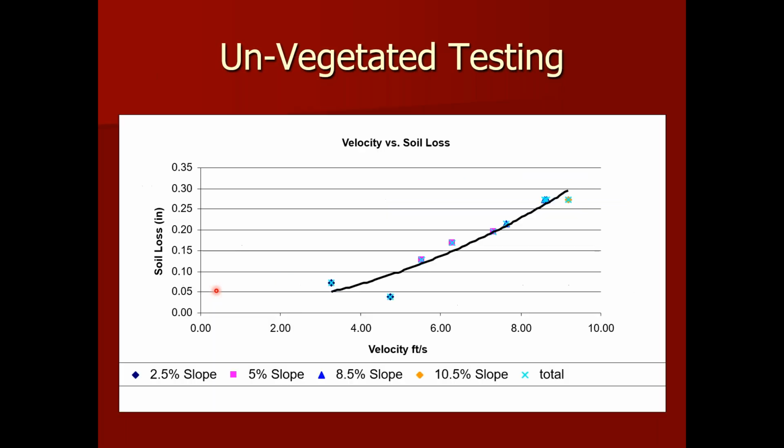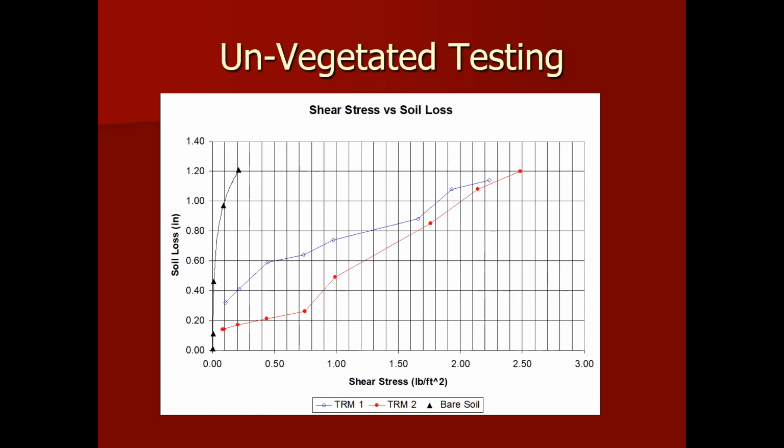So this plot shows shear stress, and certainly the same type of situation holds with velocity. As I said, ASTM really calls out shear stress right now. Personally, I always look at both. Physics is physics, and so the lift and drag are probably equally important. So you want to be able to quantify, as we have here, the effect of velocity on that soil loss also. What it means to designers is at the end of the day, we have plots that look like this.